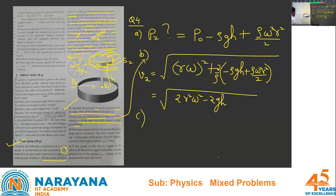D is in fact the best one. Now in C, he says, if the tank rotates too fast, the pump efficiency drops, and that is because of cavitation. So he's talking about something called cavitation. So if you make omega too large, then it will cavitate. So what he wants you to do now is, what is the highest cavitation-free angular speed? What is omega max? And that should be cavitation-free.